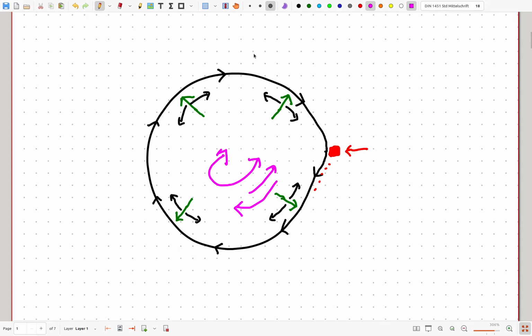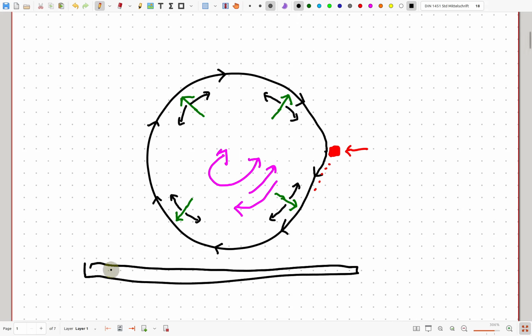So let's think about how we might implement this kind of idea digitally. And really for a delay line in a digital system, we've really got two options. I mean, a delay line in a digital system is a buffer of memory, a linear buffer of memory, where we basically store lots of different numbers in a line.